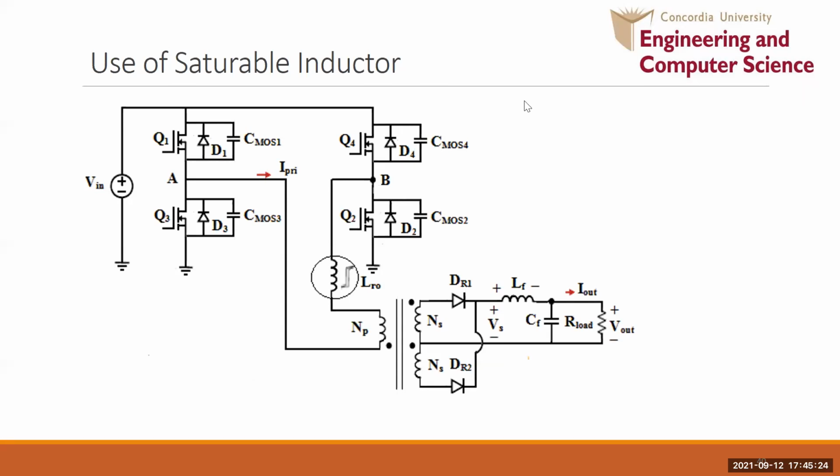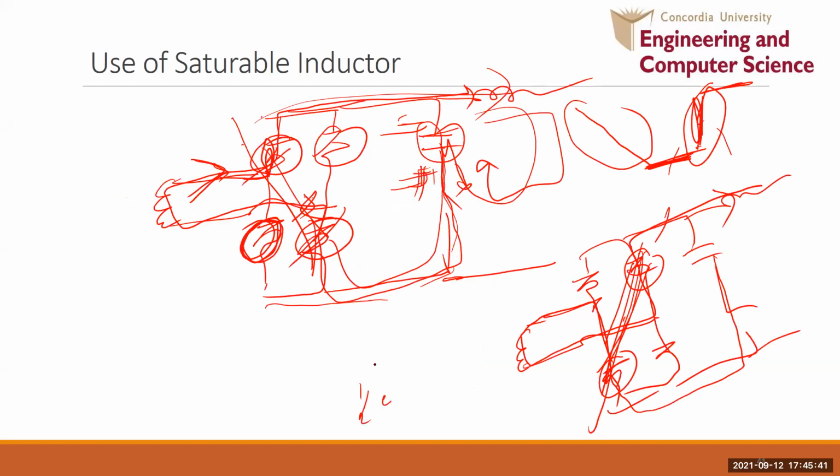If we think of soft switching, gallium nitride devices have low capacitances. When we were talking about half CV squared, half L i squared should discharge the half CV squared, where V is V in. If C is very low, then this energy is low.